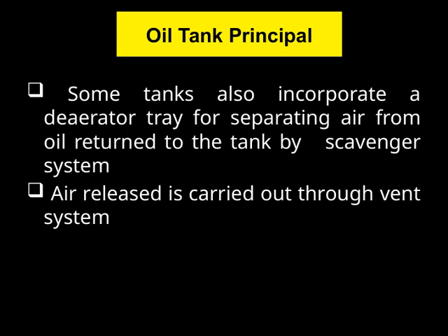On this slide, we're looking at some tanks that include a deaerator tray. This component plays a crucial role in separating air from the oil that's returned to the tank through the scavenger system. Essentially, as oil circulates back into the tank, any entrapped air is removed by this tray, helping to maintain the oil's quality and prevent issues like cavitation or foam formation. Once the air is separated, it's carried out through a vent system, which ensures the tank remains properly ventilated and